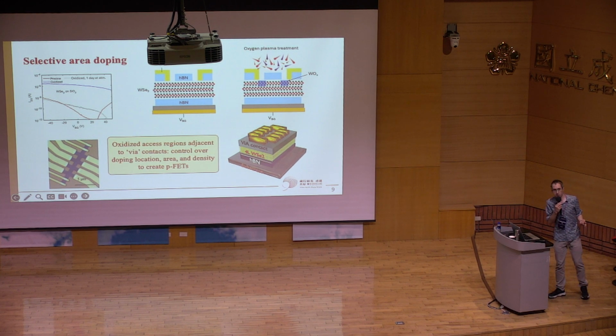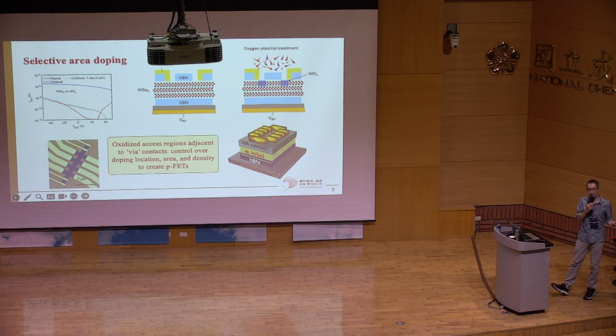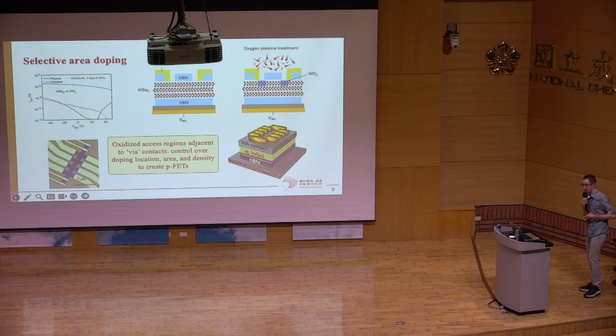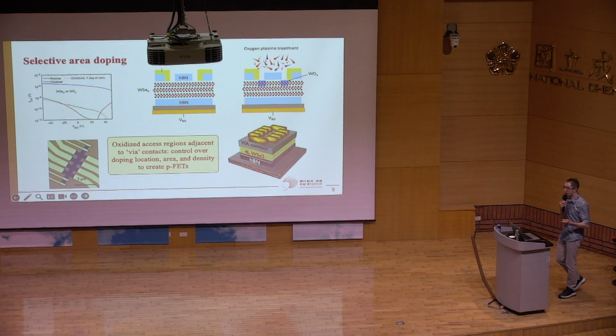Now there's a solution, and that is just to wait. But there are two problems with that: one is how long do you wait, and two is what environment do you leave it in. It depends if you leave it in ambient, just in the air around you, or in an inert atmosphere like nitrogen, or in a vacuum. That will change where this threshold voltage ends up.